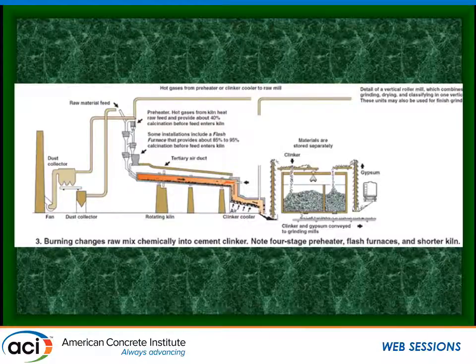We're heating that stuff up to about 1,800 degrees Celsius or 2,700 Fahrenheit. And at that point, all of these compounds that we've mixed together are going to break down to their elemental state, and then recombine based on the total combination of those materials that we have in there. So it's a giant chemical equation that we're solving, and when we're running a cement kiln, we have to account for every component and every ingredient. For example, when we started burning tires as a fuel, a lot of tires are steel belted. Well, the carbon black, the tire rubber, burns very efficiently and it all goes away.